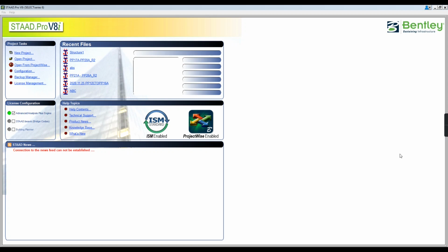In this method, you will be analyzing your slab, then you will extract your forces Mx, My and Mxy from your model, and then using a simple spreadsheet or Excel sheet, you can design a slab by this method. Now the second method is by using a design command and then getting reinforcement from the output file.